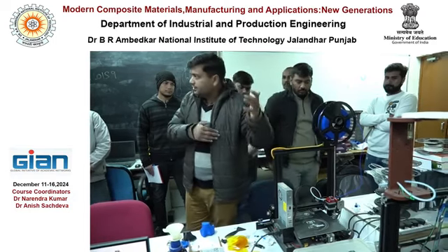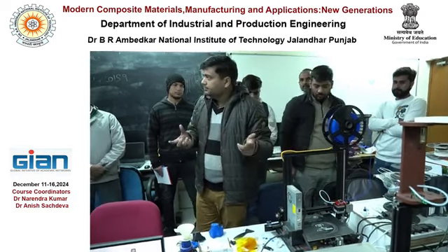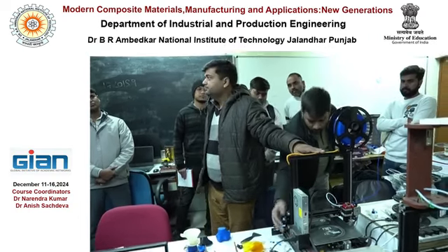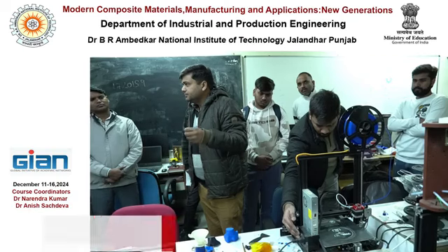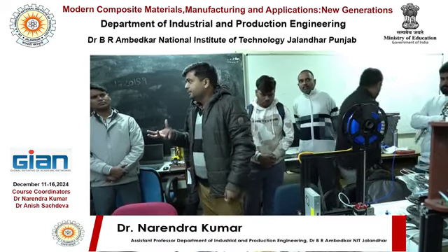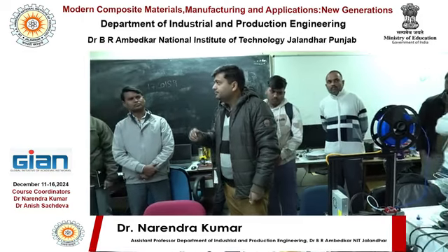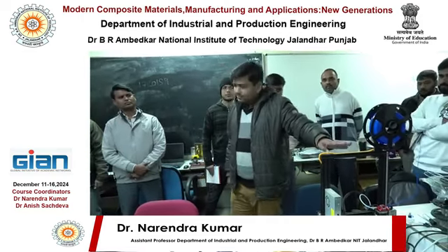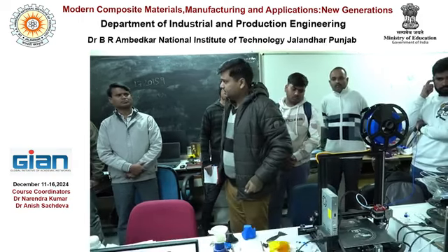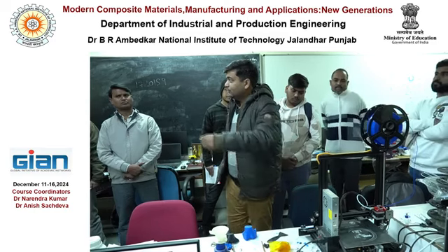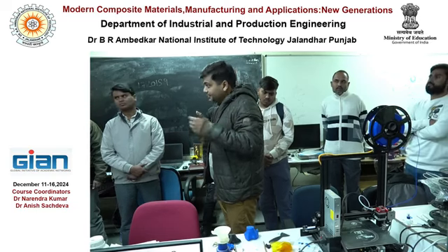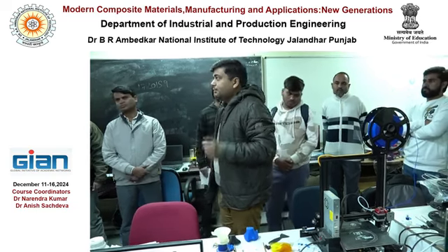When this was invented, they used this technology only. That's why this technology became very popular, because it's simple to operate, simple to use, a very simple mechanism. Only heaters are required, and one motor is required to push the material. If you guess the cost of this printer, it is available for only 12,000 to 30,000 rupees in the market. The laser-based mechanisms are costly because the laser itself, the power source, is very costly.